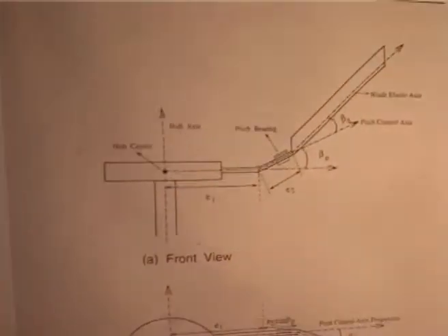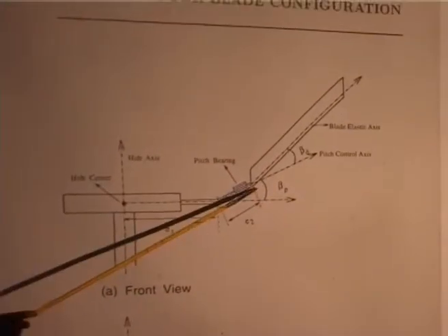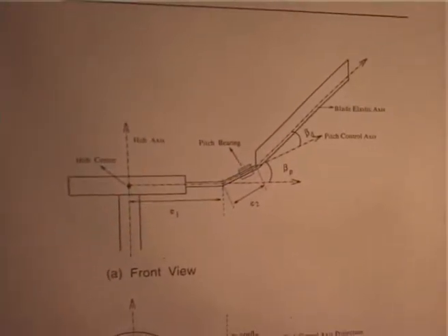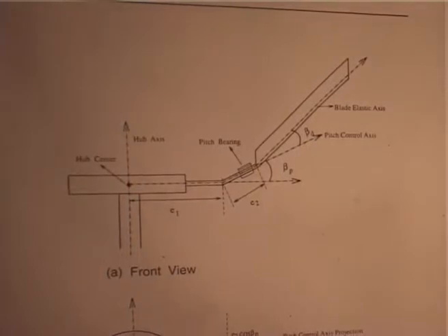These are all geometrical. The order is about 2 degrees. You know the effect of pre-cone is to relieve the root moment, but it has a tremendous aeroelastic coupling influence in terms of damping. I have shown here the difference between these two. I am not sure whether one blade has both.